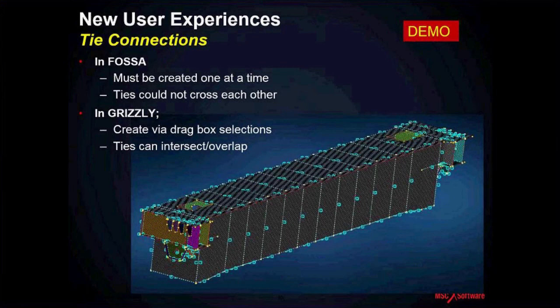What is the advantage and disadvantage of that situation? Once we stitch the parts and move all the parts into one, it becomes a single monolithic structure. And once we do the baseline analysis, it's almost impossible or difficult to make any design changes because the original product structure is lost.